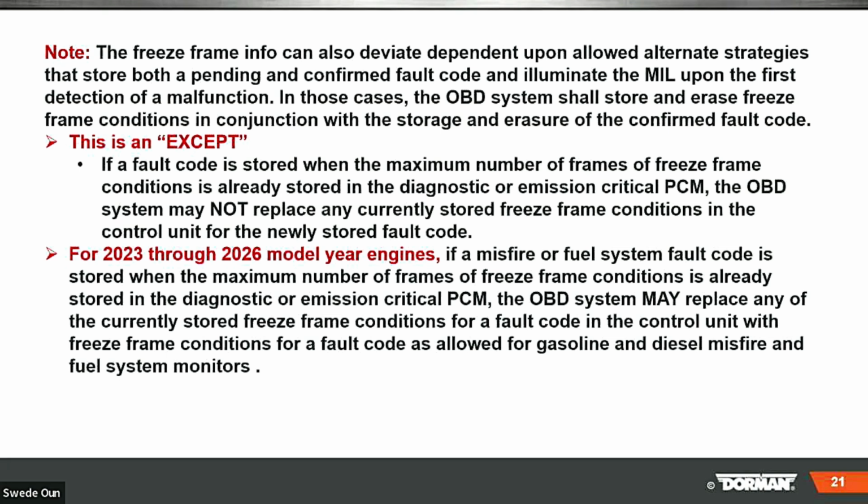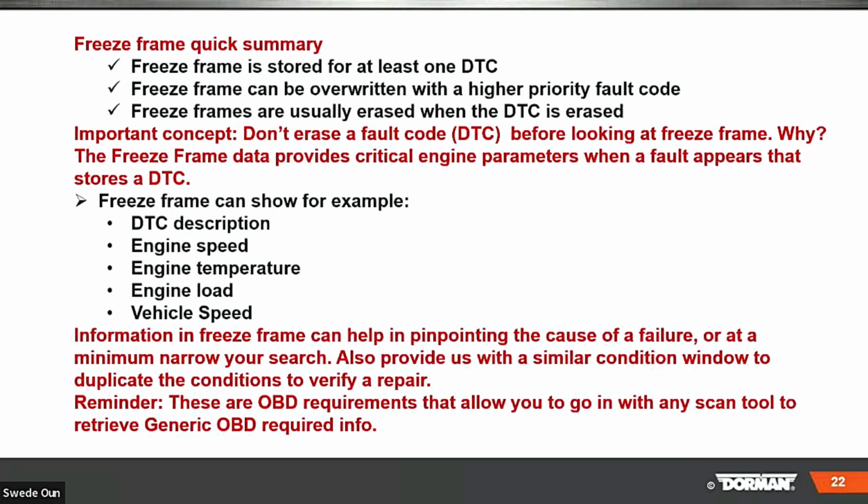And like I said, if you choose to, mull over this. There's a lot of information about OBD2, and I'll be very honest with you, you get some good stuff. I see Gene over there, plus always run the monitors, check the mode 6 after repairs, absolutely. But also, there's a lot of information out there.